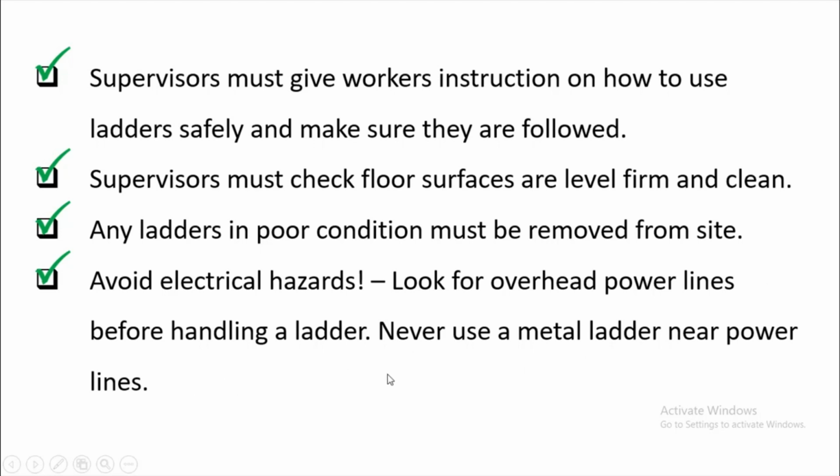Okay, when you are using the ladder, don't lean the ladder on the cables or power lines, because especially if your ladder is made of aluminum, it is a very good conductor, so the user of the ladder will get electrocuted.